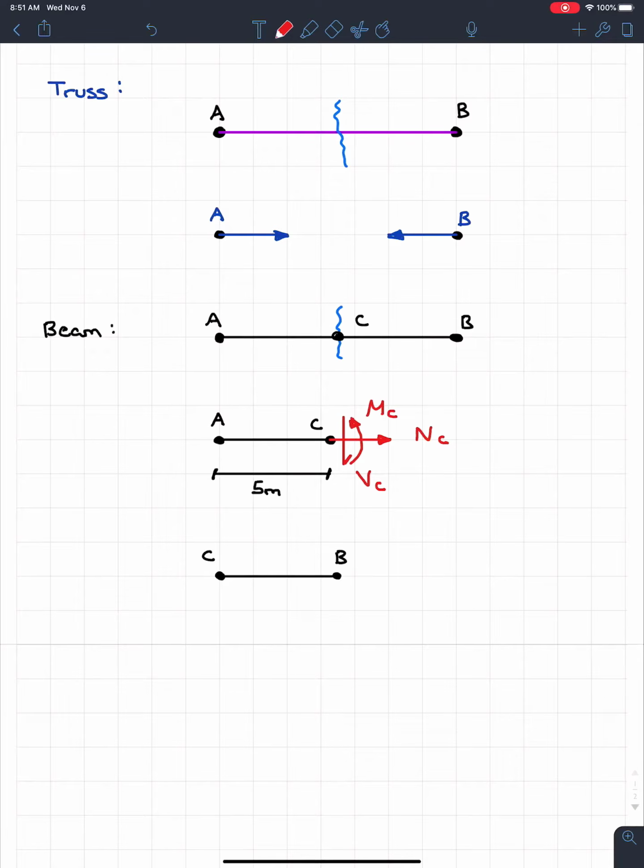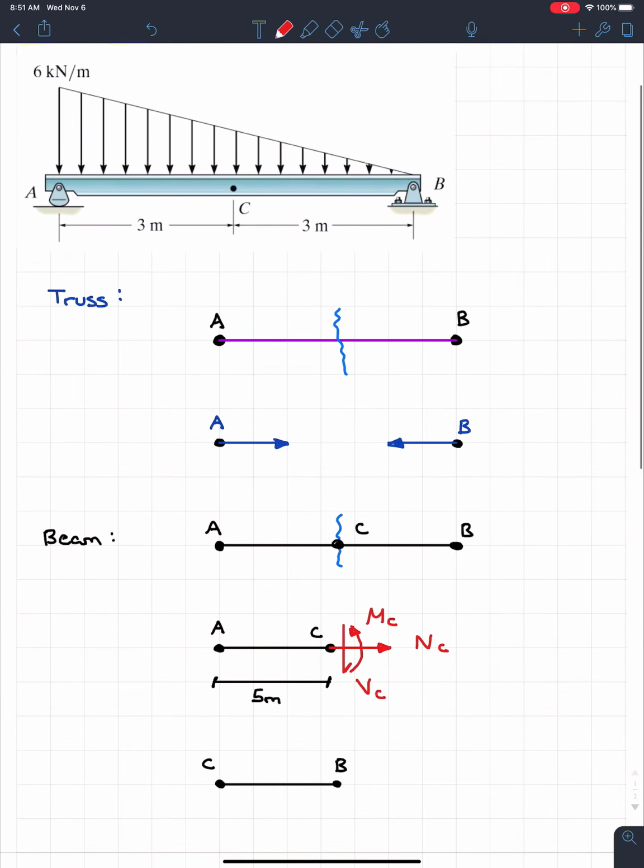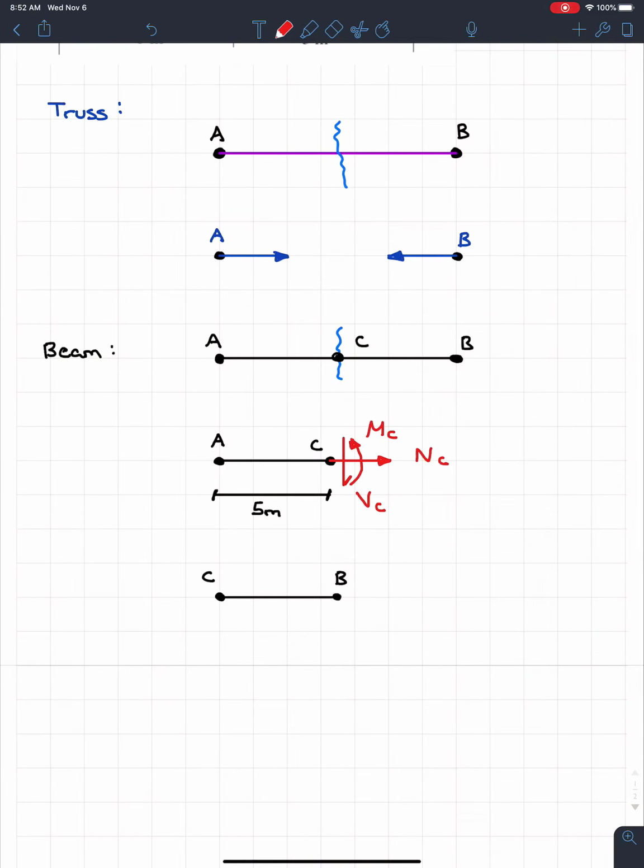And that's very, very special because remember, for a truss, every member that we cut resulted in 1 force. So we would always say, well, we have 2 equilibrium equations. We can only cut through 2 members or 2 unknown members at a time. But if we look at beams, however, we have 3 unknowns. And we have 3 equilibrium equations. And the third one we can actually use for beams is because we deal with distances. It's not like trusses where everything acts at a point now. We have that distance, therefore we can use sum of the moments.